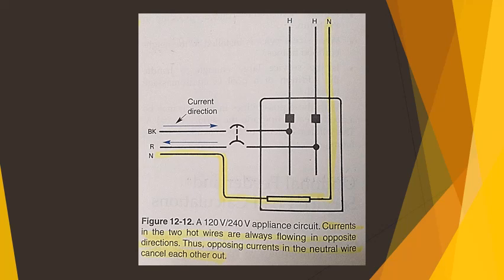Just as a side note, your calculated service amperage size for your OCPD or your main breaker is not so much the protection for the panel, but the amount that you envision the house to be limited by.